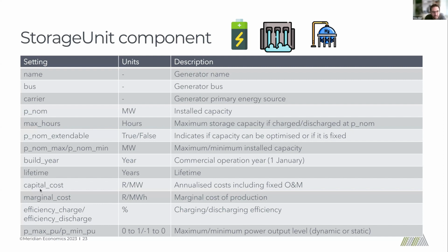Then the capital cost that you specify, it's very important that it's on a rand per megawatt basis. So often you will have storage capital costs on a rand per megawatt hour, but you have to make sure that you use the max hours with the relationship between megawatt hours and megawatts. So your capital cost for a storage unit is in rands per megawatt.